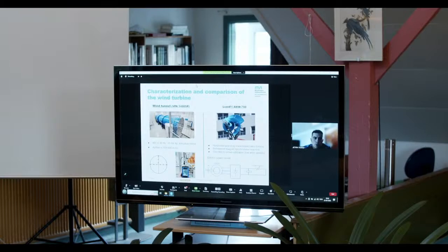The first step is to familiarize ourselves with the wind tunnel that has been used during this project. This wind tunnel is commanded in frequency, so we control the wind speed by changing the frequency set point. To obtain the wind values that the turbine is receiving, an average has been calculated from the winds recorded in 9 different points. In this way, very accurate results have been obtained.